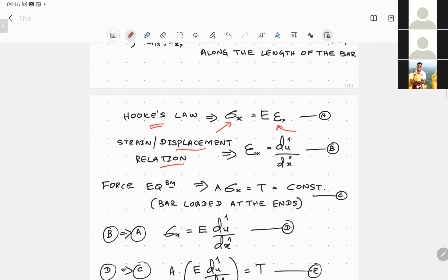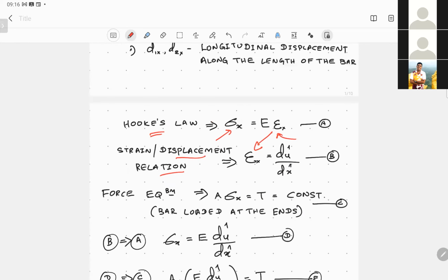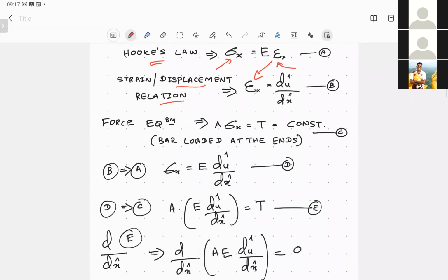We started with the stress, and we are analyzing the strain now. The strain can be written as du hat divided by dx hat. Dx hat, for that particular direction, let's consider it to be the initial length, and u hat gives the displacement function for the particular direction in this case.